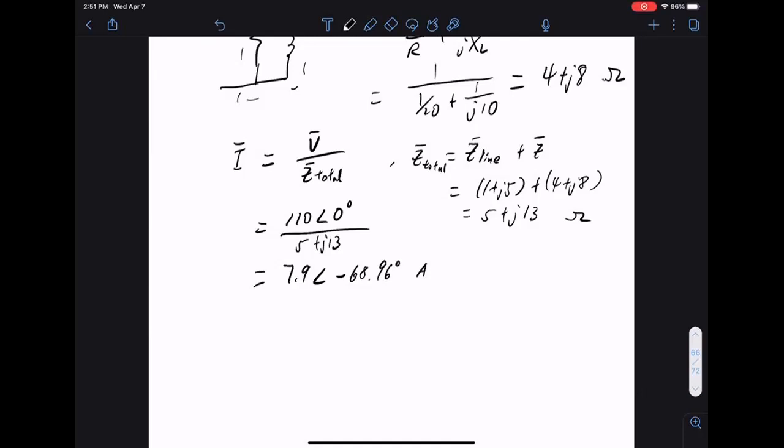We go through and find the source current for part 1, and then part 2 asks us for the real and reactive power. So I did the VI cosine theta and VI sine theta, and you just take the magnitude from the phasor since VS is given as a VRMS, so it's just the 120, and then we use what we found for the source current, but we don't divide those by √2 again.